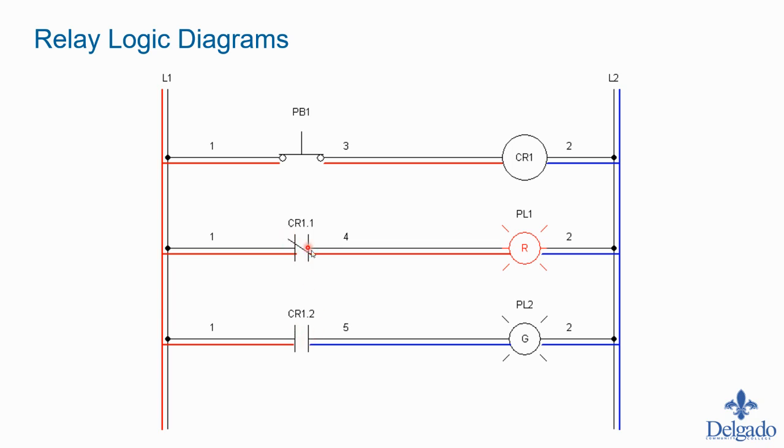We would not necessarily change its representation on a drawing this way, because we always want to represent on a drawing what the shelf state, or unpowered state, is. So we would not want to change this on a drawing, right? We would keep this normally open, but for illustrative purposes, they're showing this contact is now closed and basically passing power. It changes state from off to on, and this one changes state from on to off.